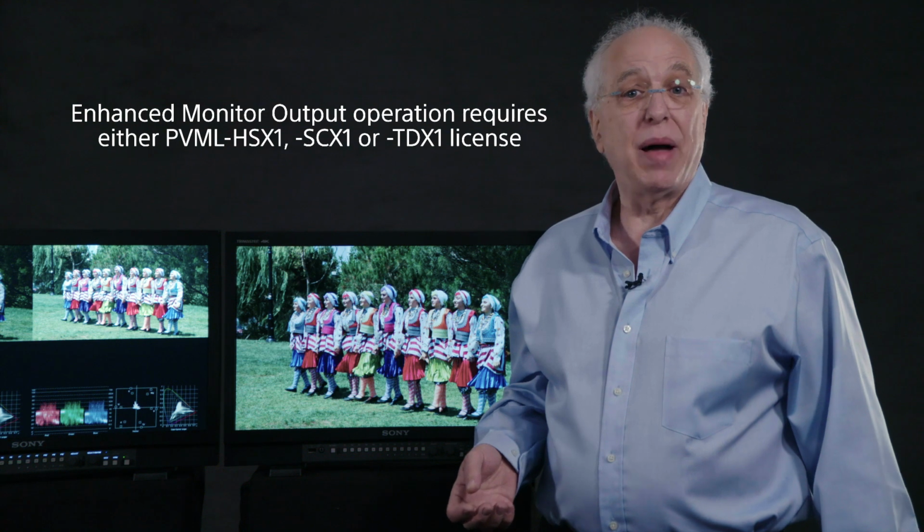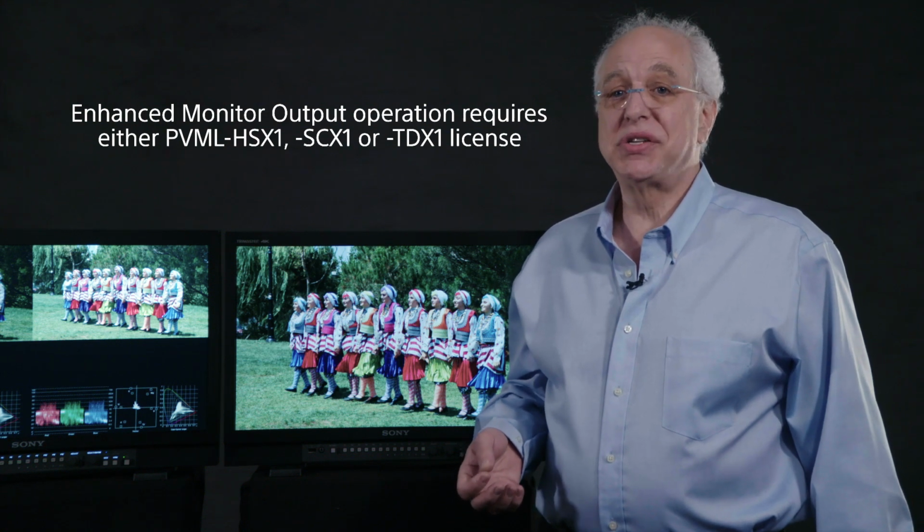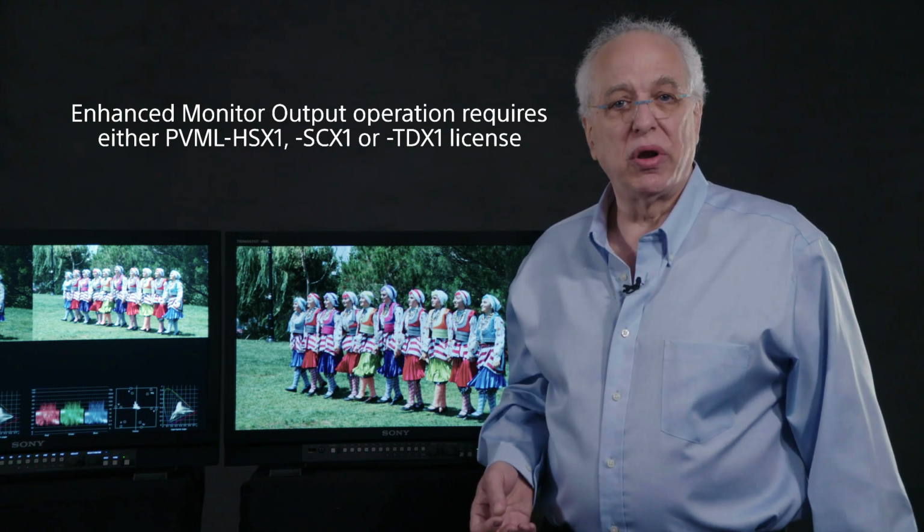Well, that's it for the PVM-X's built-in conversion engine setup. Now let's have a look at how to properly set up the PVM-X monitor for a simple LUT-based conversion of your image. You can apply the LUT data to your signal input to display on the screen, or you can output the rendered signal as an SDI signal from the Enhanced Monitor Out connector with the optional PVML-HSX1, SCX1, or TDX1 licenses.